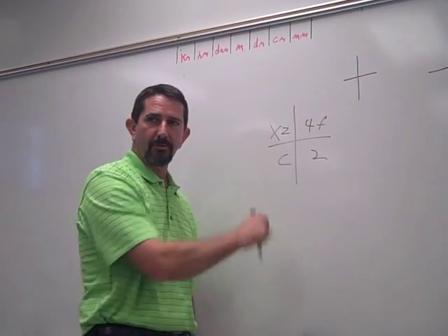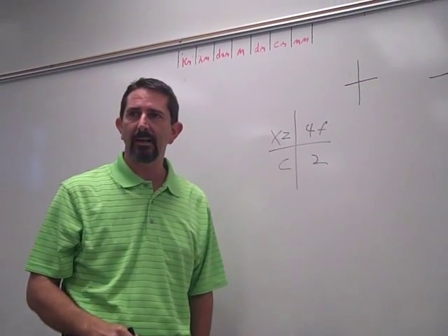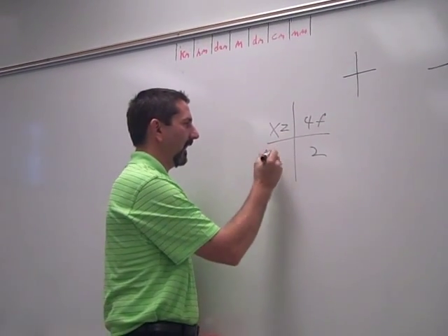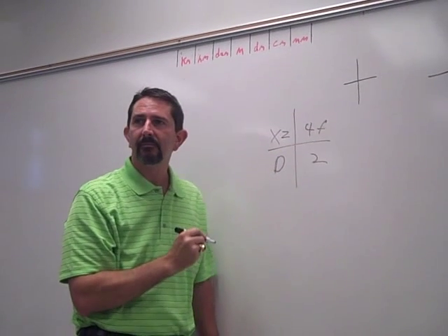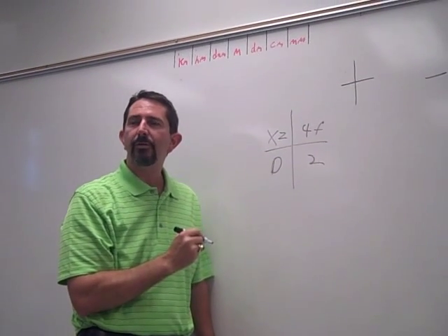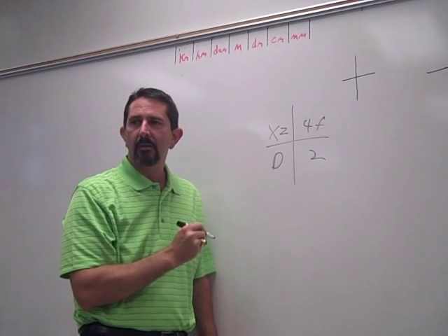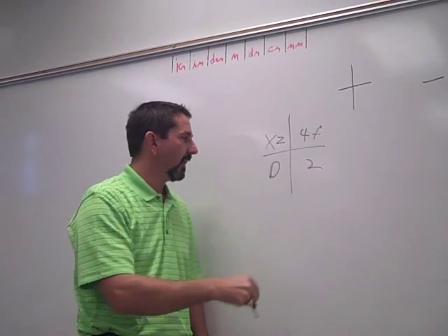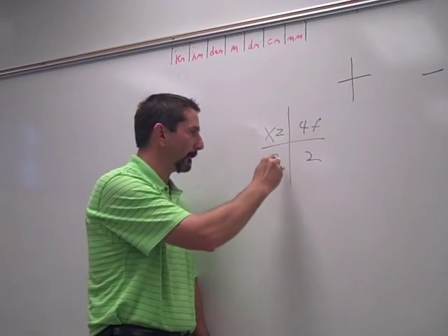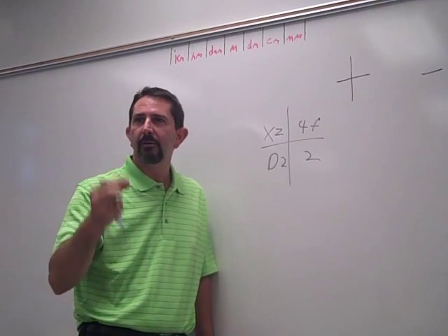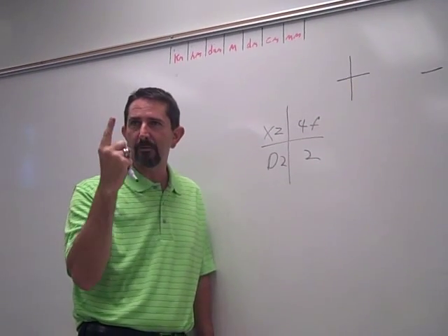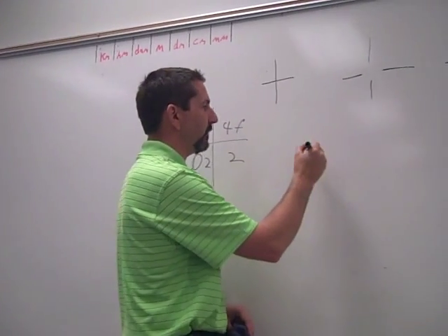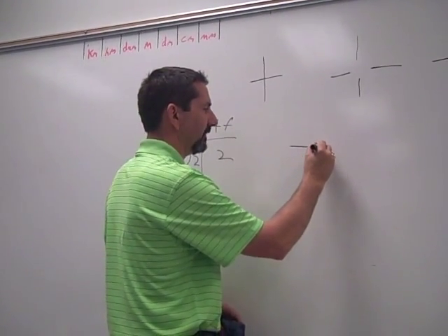Now, let's talk about this quadrant right here. Countersunk is not the only item that you could have. You could also have a D. D would tell us that we are going to dimple a hole. That is making a mechanical impression in the hole for the countersunk fastener to fit in. And if it had D with a number, we would know that it would go through 2 sheets. Because you could dimple just the first sheet, you could dimple the second sheet, or however many sheets it's going to go in. Now, the difference between a countersink, I believe we talked about this.